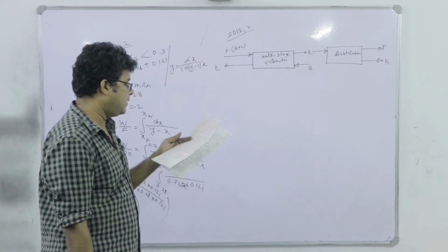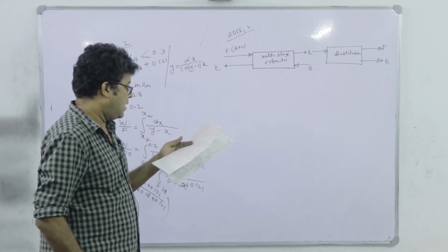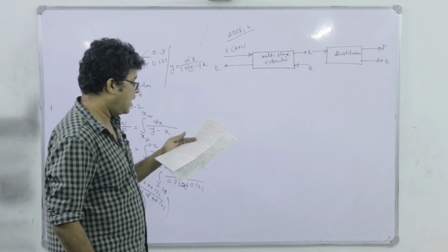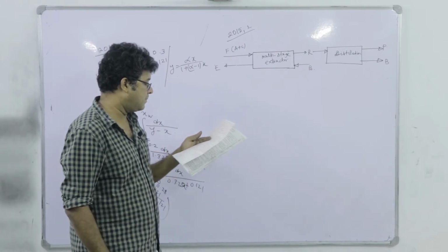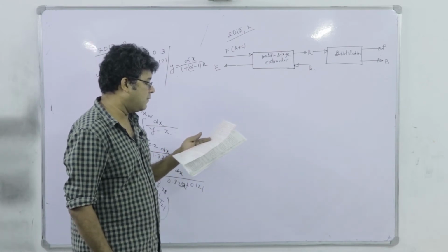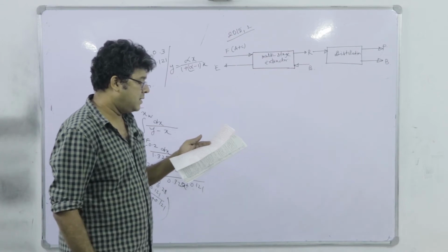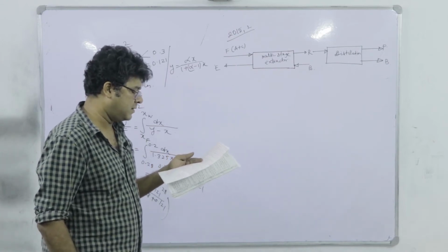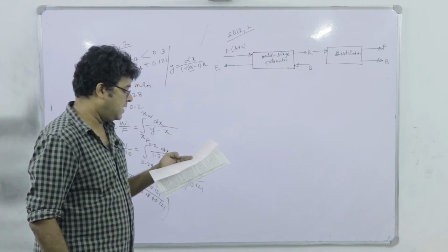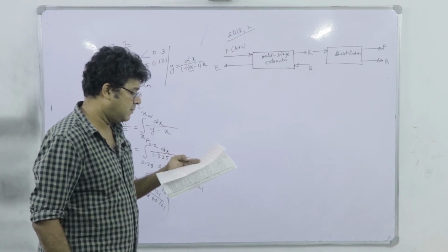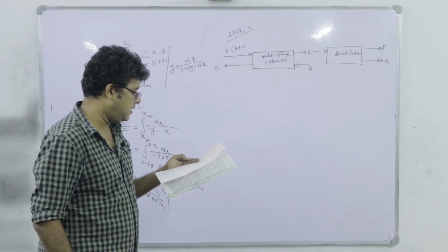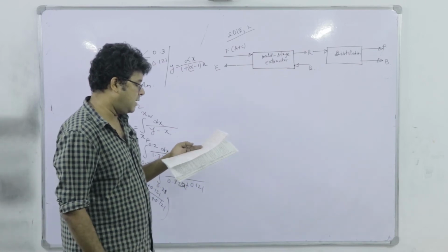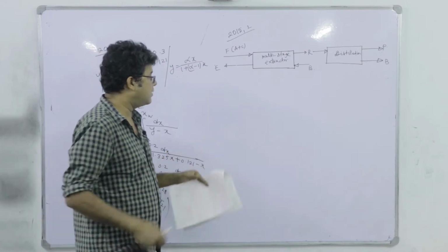Location of different mixtures for the process are indicated on the triangular diagram below. P is the solvent free raffinate, E is the extract, F is the feed, delta is the difference point, which is indicated in the graph. The line PB intersects the binodal curve at U and T. The line P delta and FB intersects the binodal curve at V and W.